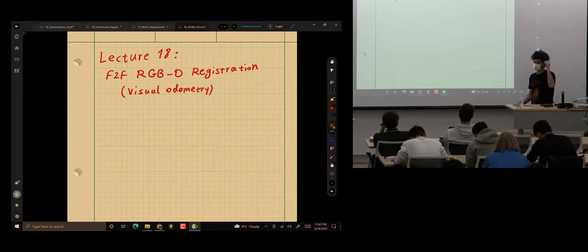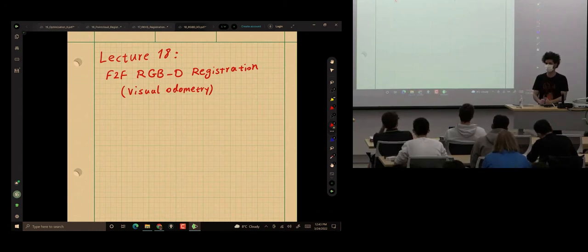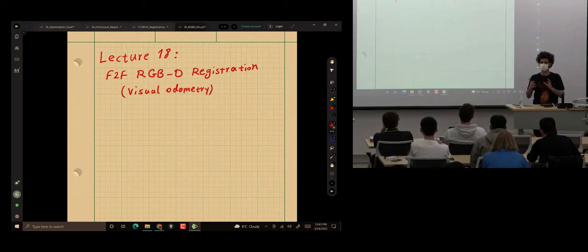Now, visual odometry does not need to be just one frame to another frame. We could work with a sequence of frames, and that's usually how it's done. That's called a sliding window optimization. Or we could just maintain the entire history similar to SLAM. But when it's odometry, that means that there is no global loop closure. There's no history tracking where after a long time we come back to a place and know that's the same place, and we try to remove drift. When we have that, that's SLAM, simultaneous localization and mapping.